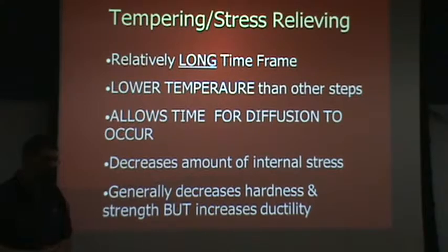First, there's one particular segment of temperatures that if you temper in that range, you actually tend to make things more brittle. When we were talking about the letter openers that you guys made, we were looking at tempering in a range up to about 500 degrees or just a little bit more than that. And then we said we would tend to avoid the range from, say, 550 up to about 800.